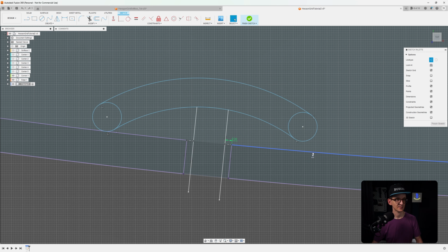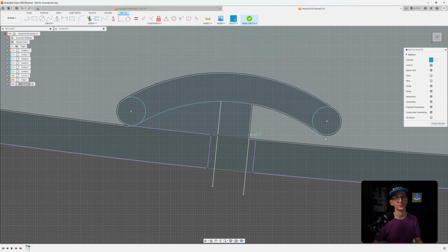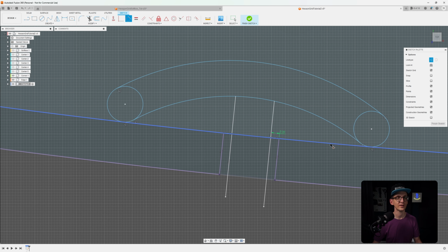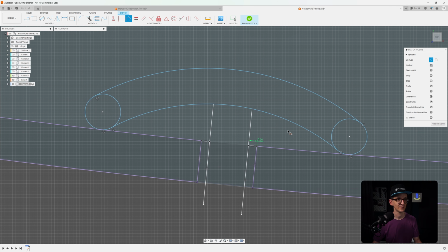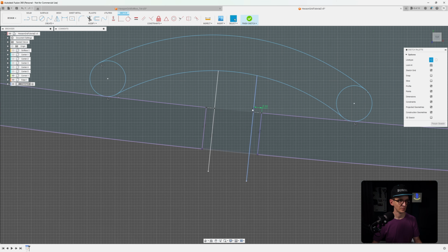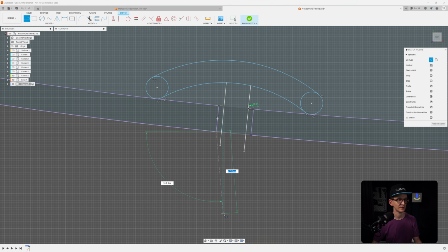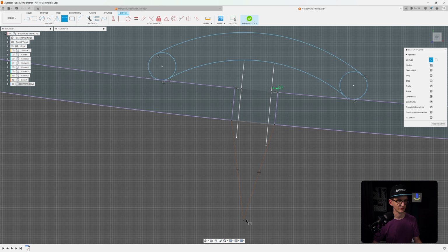And sometimes it happens that such a constraint completely messes up everything because it's not constrained enough yet. So it is really helpful to keep it as close as possible usually. And that in most cases is enough to not ruin everything before we have the chance to constrain it correctly, I would say. What we now need to do is fix this point in place, and we give it definitely the right distance and make sure it's actually sitting in the middle, and then also define how far away that should be from this point, which is in this case, I don't know. It looks actually quite well. So maybe let's make it 5.